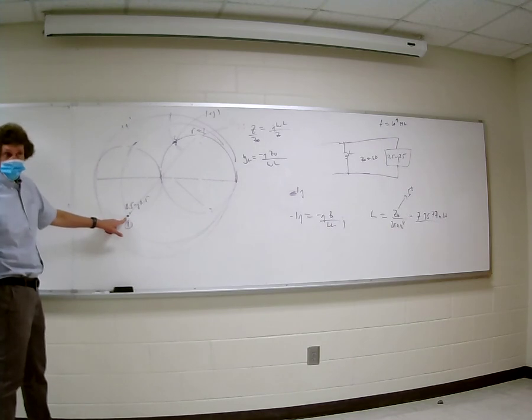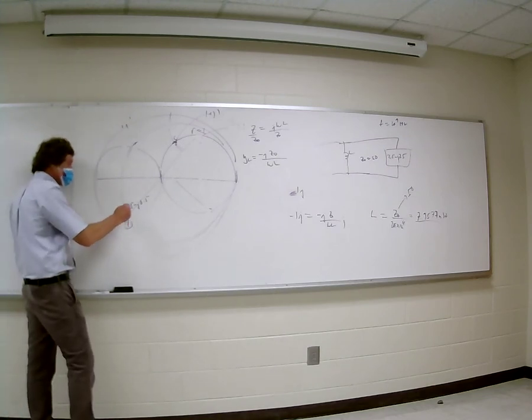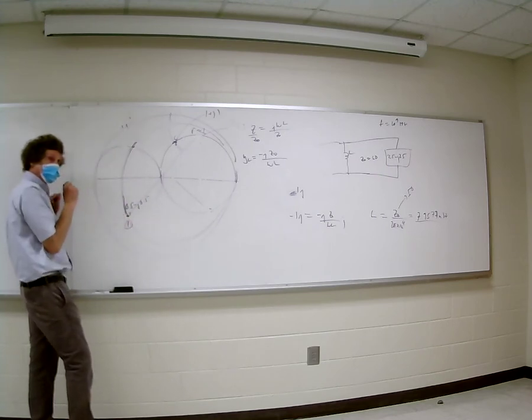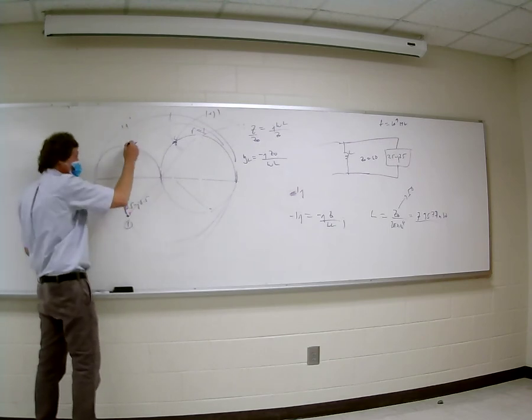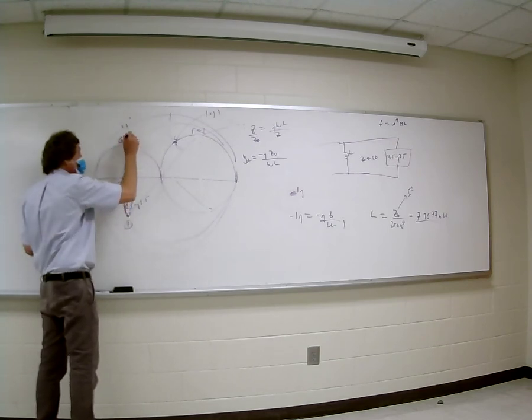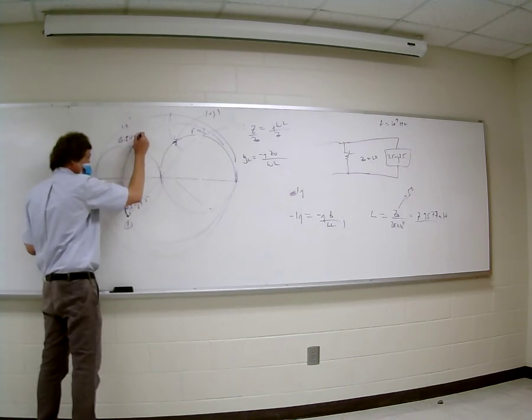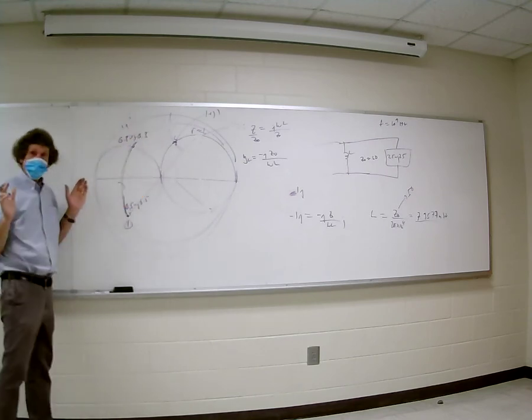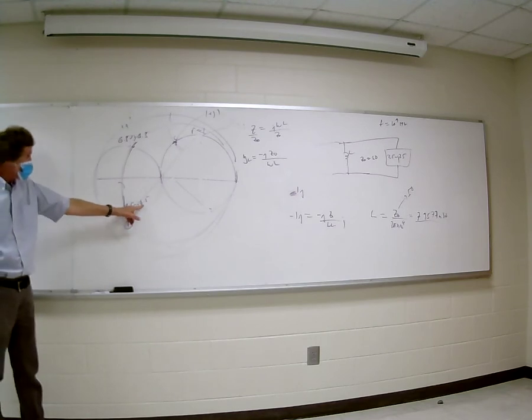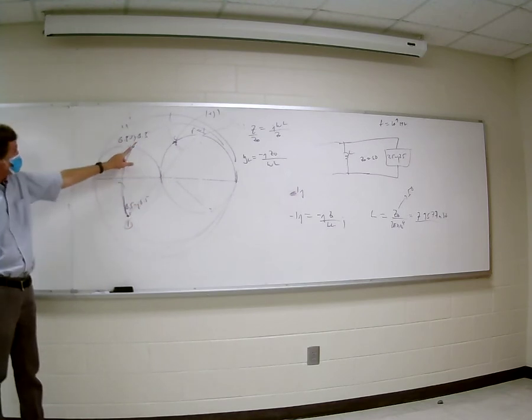Now listen. If we added an inductor in series, remember this is impedance, right? It's normalized. So if we added an inductor in series, we would be adding plus J something, right? And we could go right to this point here, right? Y'all follow me? Then we would have the same magnitude, 0.5, but this would be plus J 0.5. Do you all agree with that? If I add it, I'm just going to get rid of this and turn it into a plus J.5. See if that point isn't on the rim right there. Y'all see it? I call it a conjugate point because the imaginary term just changes sign.